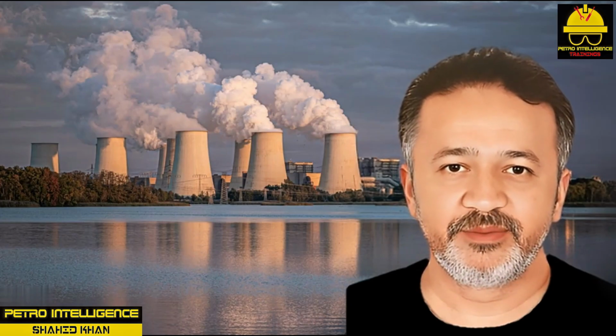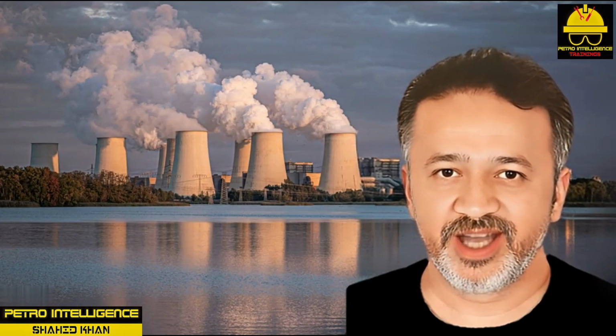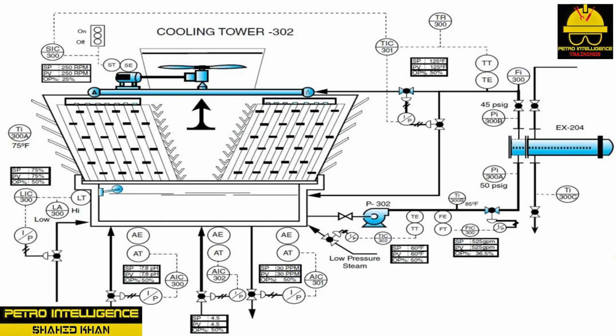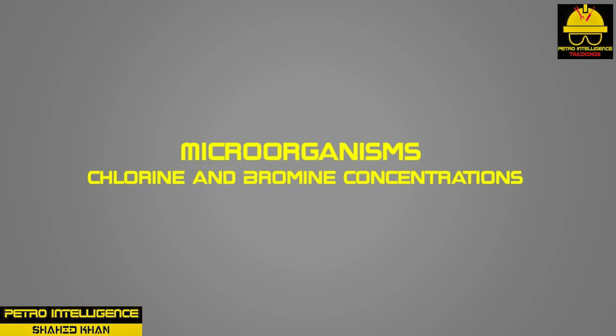Sulfuric acid can minimize problems caused by dissolved solids. Blowdown on CTW302 is timed so chemical injection has time to blend into the recirculation system. A chemical additive is added in a section of the cooling tower where turbulent flow enhances mixing and where it is not drawn into pump 302 suction before adequate blending has occurred.